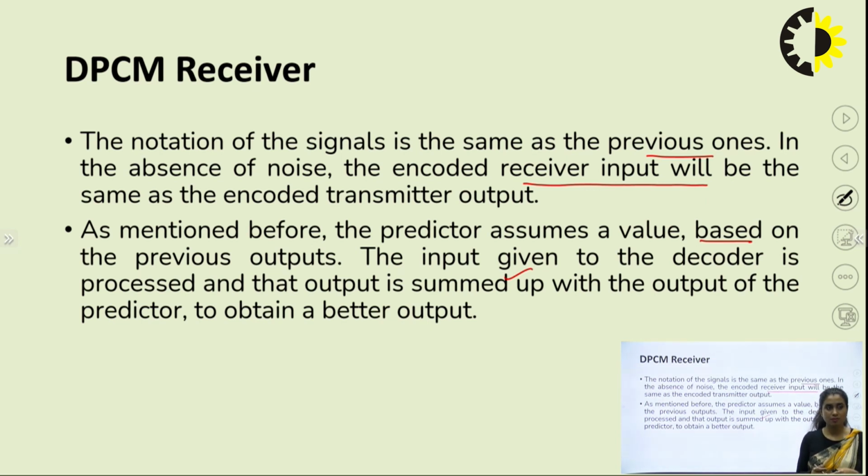If we want to talk about adaptive pulse code modulation, in that case, one thing that actually varies is the step size of the quantizer. That will depend on the slope of the input wave. So that can be taken into detail in the upcoming lectures. So that's it for today.